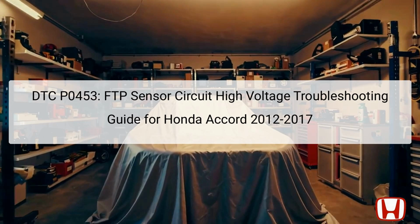This troubleshooting guide is specifically designed for diagnosing and resolving the DTC P0453, which indicates a high voltage issue in the FTP sensor circuit of Honda Accord models from 2012 through 2017. The guide provides a systematic approach to identify whether the FTP sensor itself, associated wiring, or the PCM is at fault.